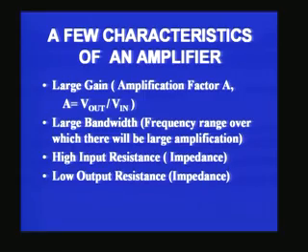Usually our audio signals, for example, are from 20 hertz to 20 kilohertz, and therefore up to about 20,000 hertz the amplifier gain should almost remain constant. Then you find the bandwidth is very good for audio amplification. But there are situations where you want to have higher amplification factors for higher frequencies also. They are wideband and several other variations about which we will perhaps discuss a little more later on.